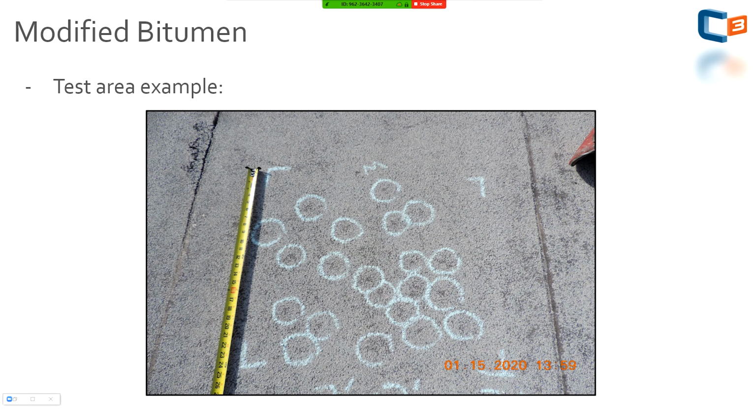A lot of single plies, you'll hear these different phrases go out, but just know it's one ply. A lot of times if it's reinforced, you'll have that suspended between that ply, but it's still a one ply system. So different application methods here. We have mechanically fastened, adhered in the middle, and then ballasted on the right-hand side. What confuses a lot of people too is how to identify what's what. On the left-hand side, you can see the circular fastener plates on the seam of the EPDM, and then you can see the square fastener plates on the substrate.